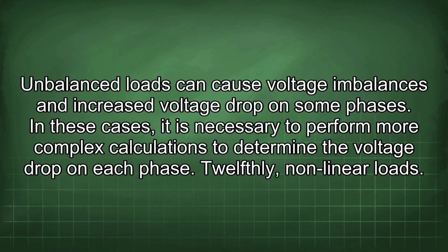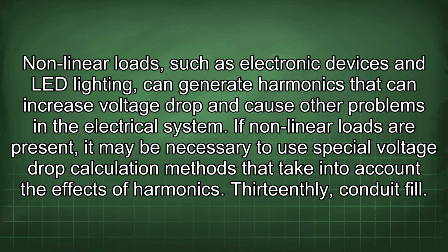12thly, nonlinear loads. Nonlinear loads, such as electronic devices and LED lighting, can generate harmonics that can increase voltage drop and cause other problems in the electrical system. If nonlinear loads are present, it may be necessary to use special voltage drop calculation methods that take into account the effects of harmonics.